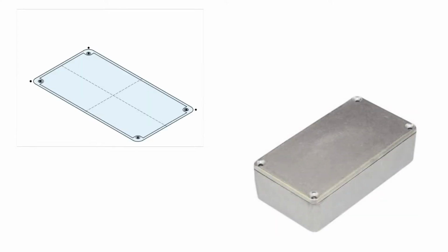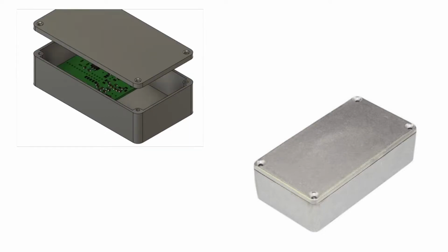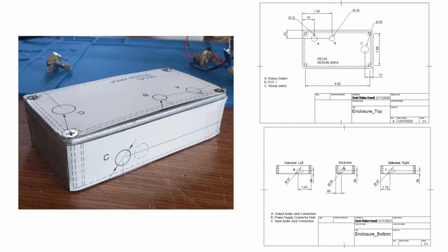The mechanical enclosure for the DIGIMUSER vocal effects processor is made from an aluminum stomp box enclosure. We laid out the placement and sizes of the holes for all the components in CAD software, and then used the CAD software to generate one-to-one scale drilling templates to guarantee accurate manufacturing.